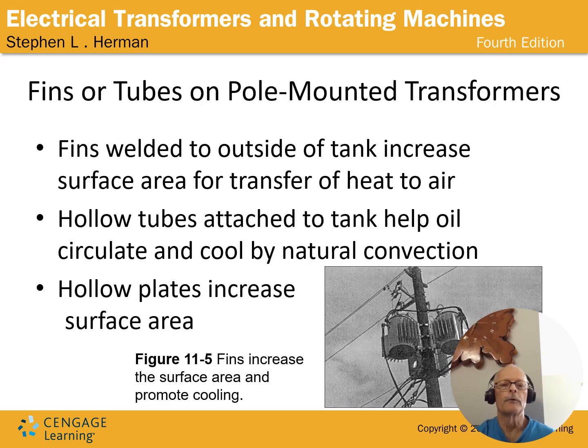Sometimes you'll see fins mounted on these, and they'll have hollow tubes in them. You can see in the picture there at the bottom corner that those are there. It's got cooling fins with tubes going up, and these things help circulate the oil. Now, instead of just running down a slick piece of metal, the oil circulates through these tubes that are open and exposed to air all the way around. That gives them more surface area, so that they can shed more heat in the cycle.